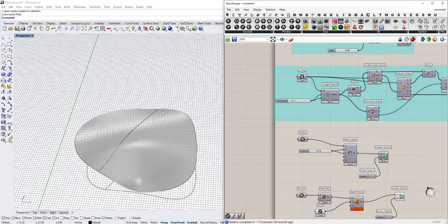It should use that as a template and kind of try to match it. You can see it does a fairly good job. Lines are now sort of flowing in this direction, and so you can use that to help determine the flow. If I put one across this way, I bet these would all start to align more with that one as well, and you would get somewhat quad facing in that direction. So that's a great sort of tool.